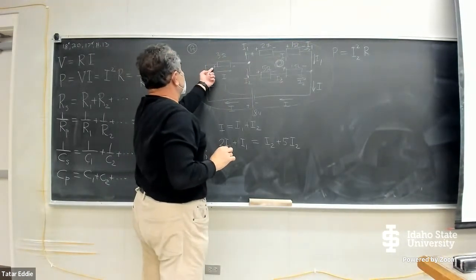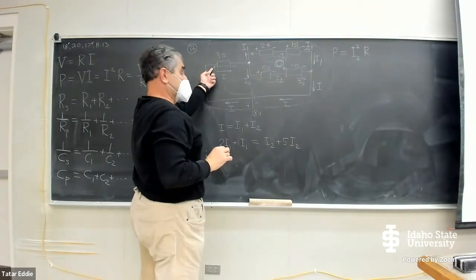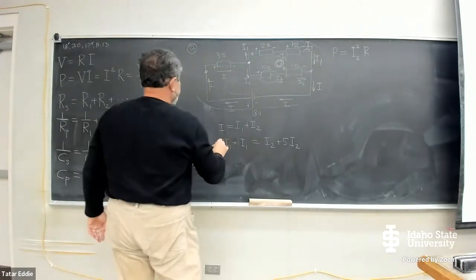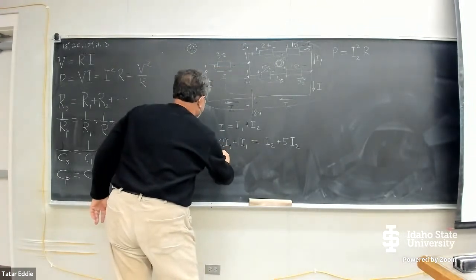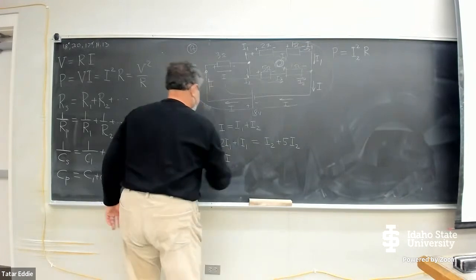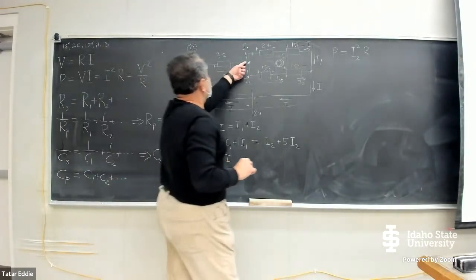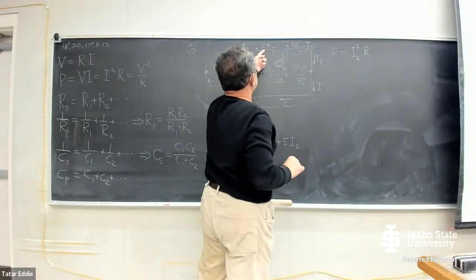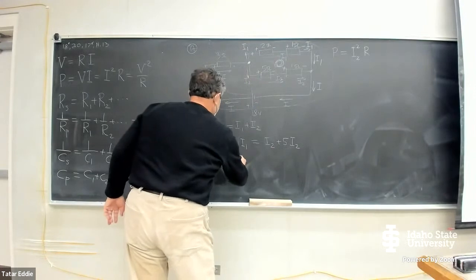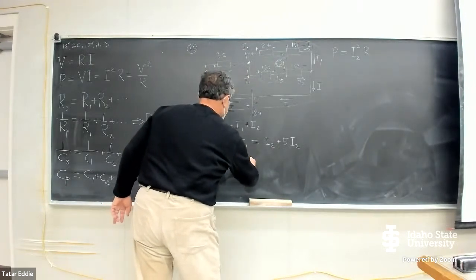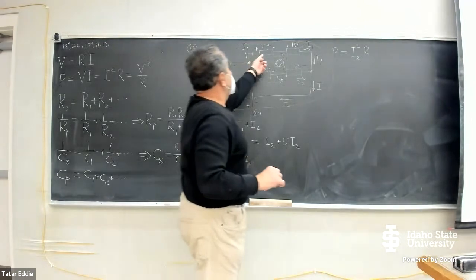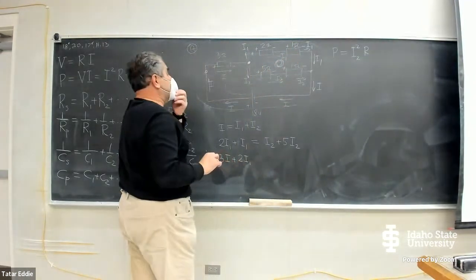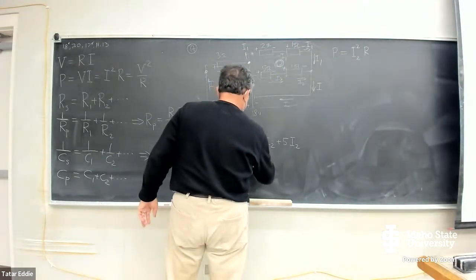I go through the 3 ohm resistor, and it is going to be a potential drop. So the potential drop is going to have value 3 times I. After that, I encounter the 2 ohm resistor with another potential drop with value of 2 times I1. I keep going clockwise. That 1 ohm resistor is going to give me a potential drop with value of I1.